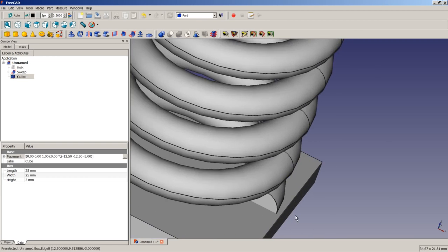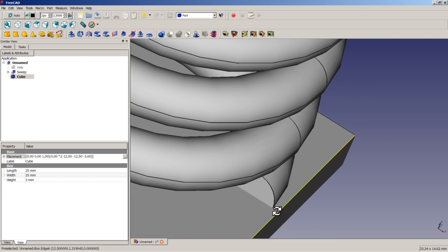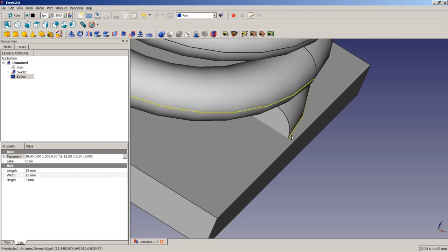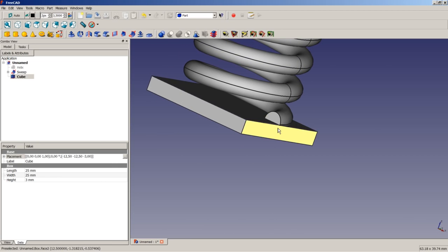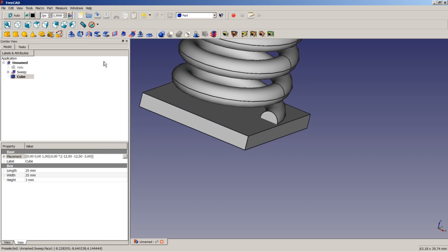Okay. If you have a closer look here, I chose dimensions bigger than the dimensions of the spring to be sure to have overlapping contours. Often with Boolean operations such as cut or fuse, especially with cut, you have problems if you don't have overlapping contours. If you just have contours which are equal, coplanar or things like that, you may be getting problems.